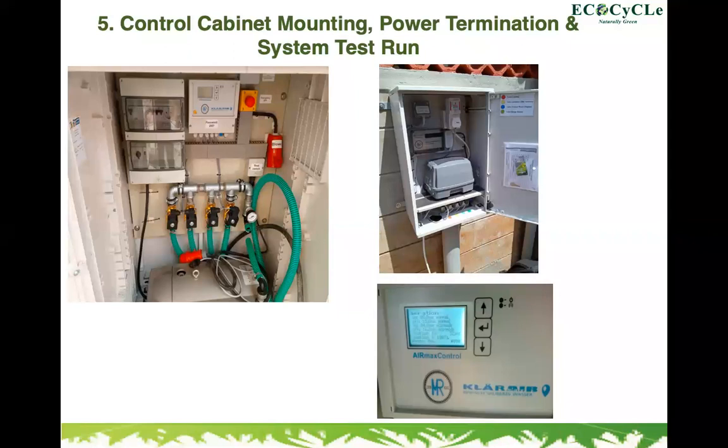The third one is responsible for the clear water discharge. Once the water is treated, the PLC signals the compressor to take all the treated water to the clean water tank. The fourth one, the last one, is responsible for the sludge return. We usually have sludge that settles at the bottom of the treatment water tank. This sludge is taken back to the buffer chamber for more bacteria formation. That pipe is responsible for that.